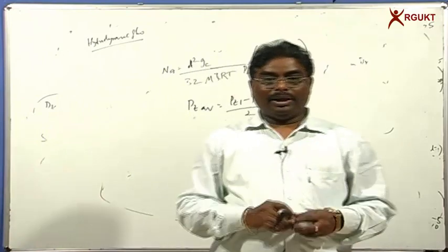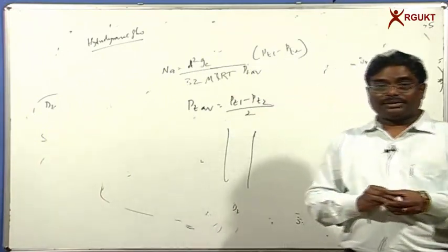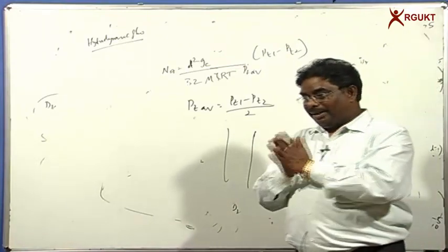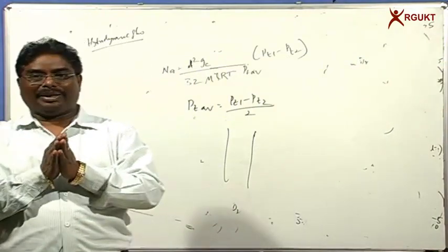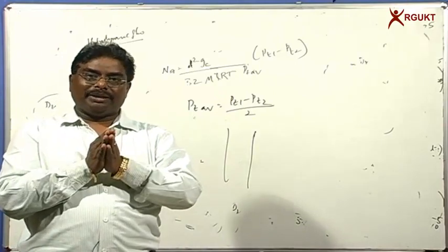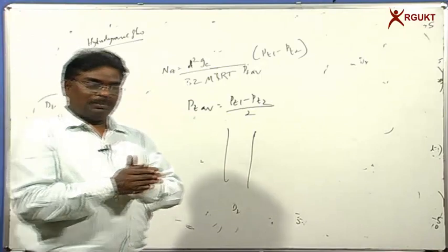So this is diffusion through solids, which we are going to come across at several places, as I told you. The flow may be taking place in a steady state fashion or in an unsteady state fashion. Even in the steady state case, the flow may be taking place through non-porous barriers or through porous barriers.